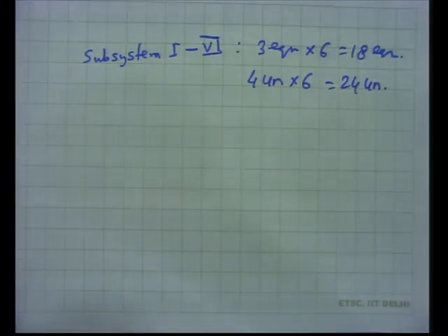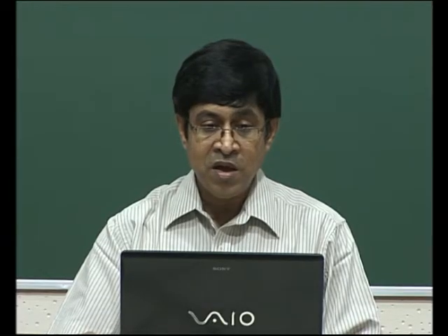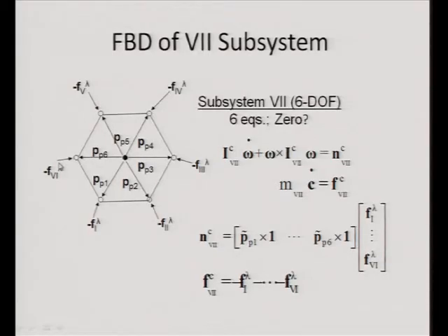The 7th body is still remaining, right, the moving platform. So, the moving platform is one body which has all these forces coming from the legs. Okay. So, this can form 6 equations, because 3 for rotational equations of motion and 3 for translational equations of motion, but how many unknowns here in this case? No unknowns, because all these f lambda related things we have considered in our subsystem.